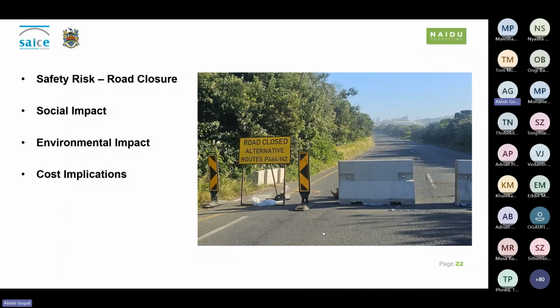While diverting the river in accordance with the Environmental Management Program, it is essential to protect the estuary ecosystem. Therefore, the depth of the new channel leading to the ocean must be continuously monitored to ensure consistent flow depth. And lastly, in terms of the cost implications, due to road closure, an alternate route was required. The cost of the traffic accommodation and associated road maintenance could have been averted if the road was not fully closed. So of all impacts mentioned and the evaluation undertaken, the most critical one was the full road closure.